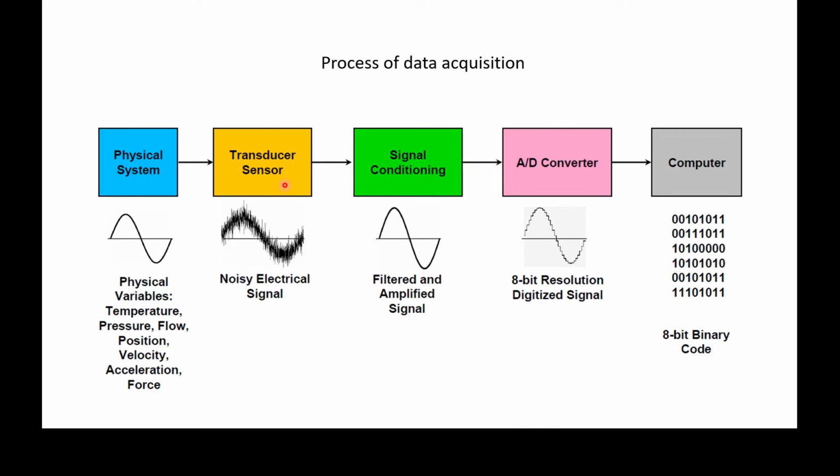And since CO2 absorbs infrared, a change in CO2 will alter the amount of infrared light that reaches the bottom of that little chamber, where we have a transducer that senses the light amplitude. So that's a complicated transducer.